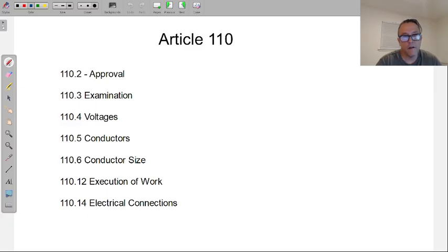All right, so you can have an outlet that has a 240 volt rating, an outlet that has a 120 volt rating. You're going to install an outlet in a 240 volt rated circuit, and you've bought an outlet rated for 120, and now you're violating that particular code section here.